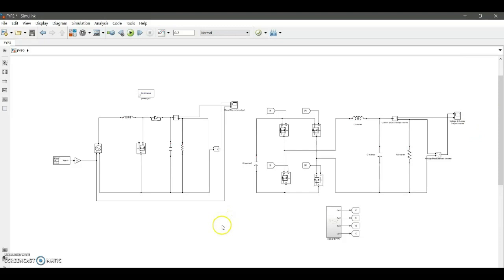And for my final year project two, I will be focused on the boost converter itself to have a closed loop system, where I vary the input from 24 volts to 21 volts, and we have a constant output at 50 volts before injecting directly to the SPWM inverter.